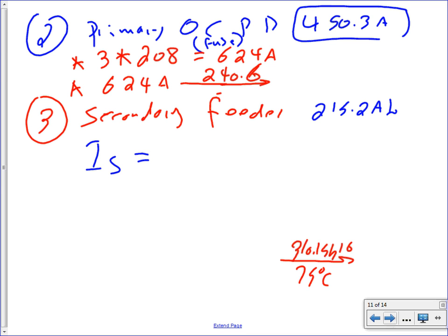So, that would be 700 amp. 700 amp. Make sense? Now, can I go for 600 amp? Yeah, the max is 700 amp. Okay, so that's the primary overcurrent protection device.